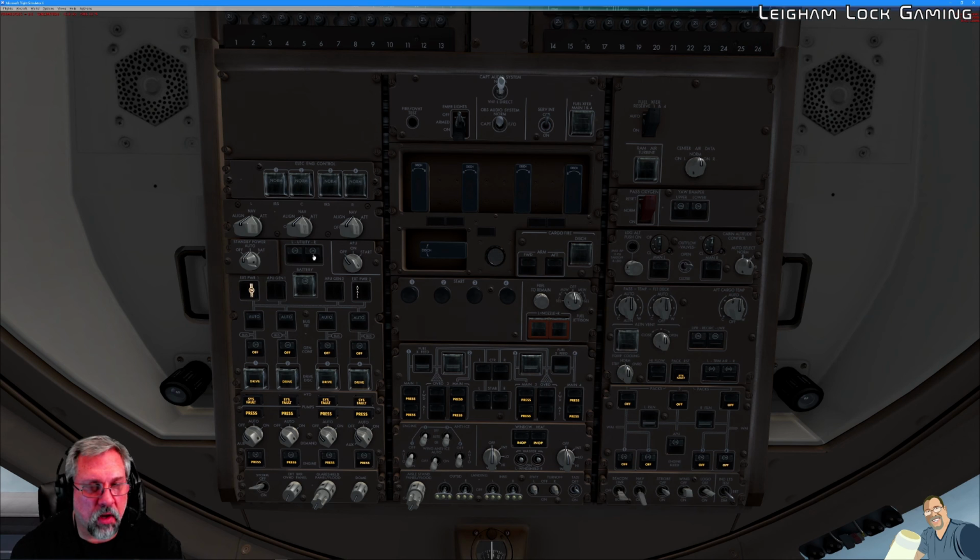Left and right utility for the aircraft, that's back in the cabin, is set to on. That is correct. Battery switch is on. We did that. The bus tie switches are all in the auto position. This is correct. Generator control switches are all in the on position, but the engines are off right now, so you have the off indicator, which is normal. The generator disconnected drive lights would also be illuminated, and they are, and they'll stay that way until the engines are started. And at this point, if it was needed, we could start up the APU.